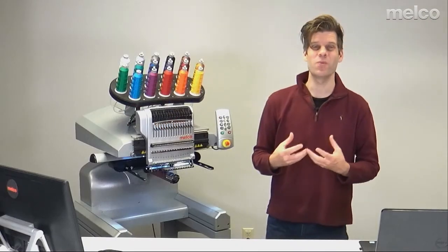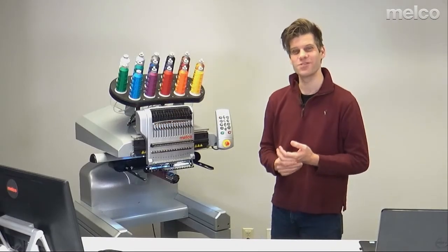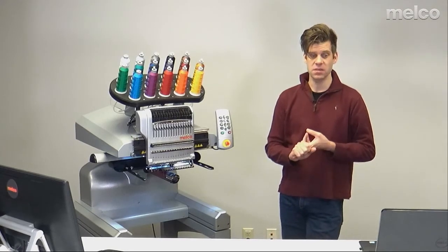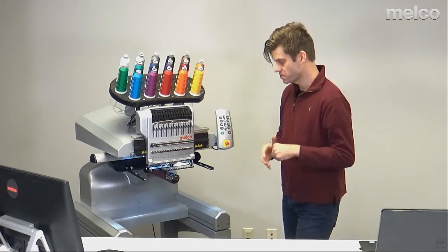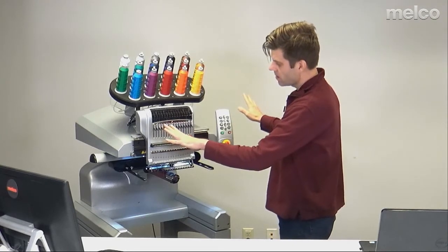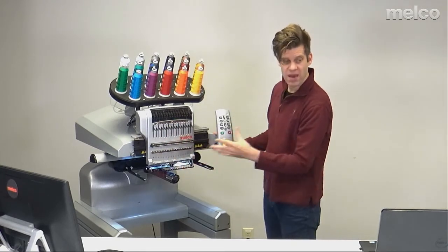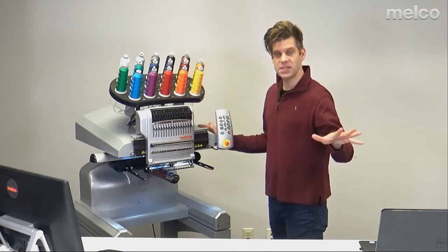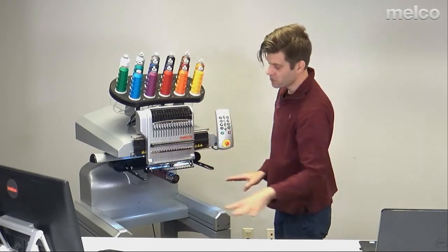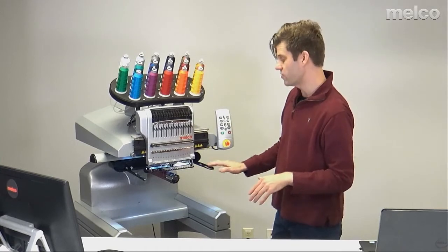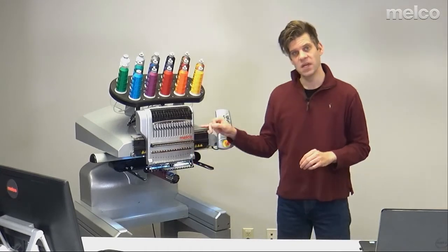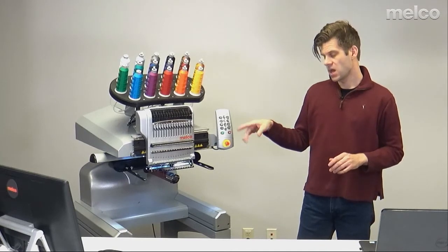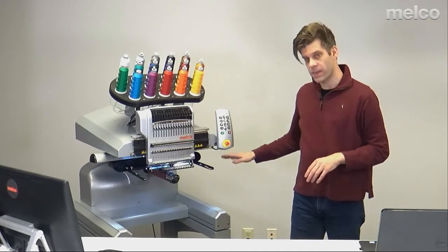Other things you may want to add to your color sequence. You may want to add an applique command or a pause command. What those commands will do is make the machine wait for you. So if I have an applique command, it's going to stop the machine wherever it meets that command, and it will feed the frame out and it'll wait for me. It'll feed the frame out as far as it can go with the needle still in the hoop limits. When you press the green button, it'll feed the frame back in and start sewing.